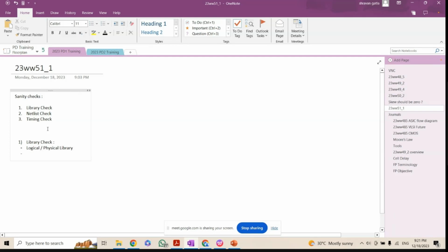Then it will lead to some glitches. A glitch is nothing but an undesired transition that occurs before the intended value in digital circuits. Let's say you're supposed to get one here, but because of the glitch, I'll explain that topic in crosstalk or signal integrity. But just understand that if you have floating inputs, you will see glitches. So glitches can also cause functionality failures.